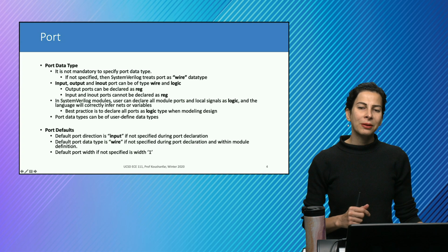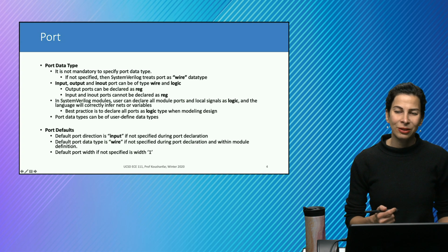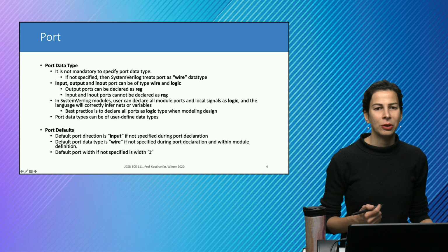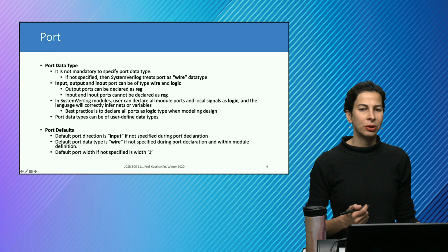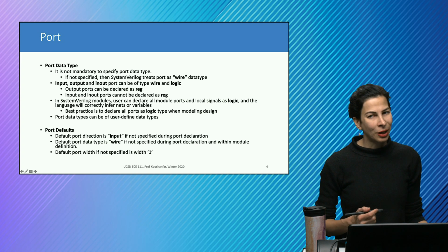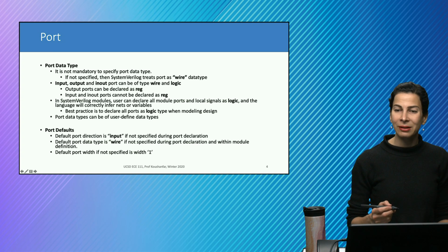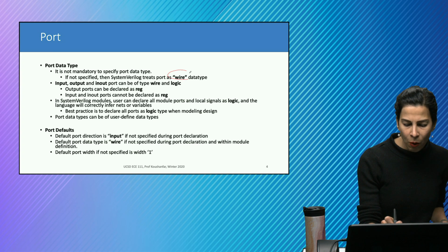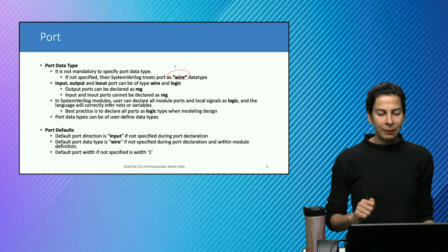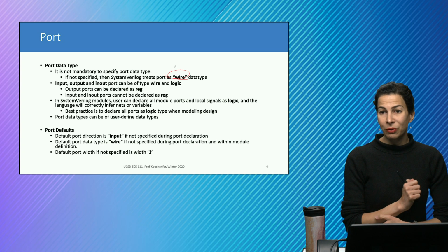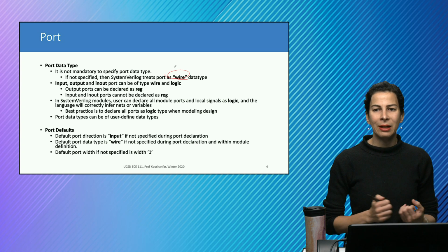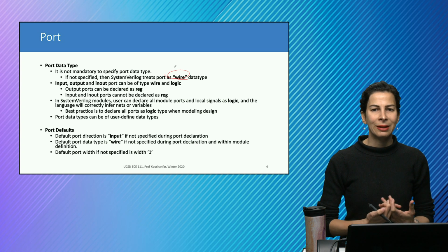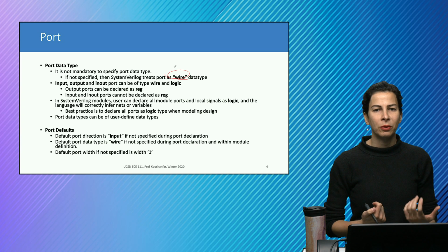It's always good practice to determine the data type for each port, but it's not mandatory. If you do not specify the data type, it will be interpreted by SystemVerilog as a wire. But if you specify it, you could specify input, output, or in-out as wire or logic.